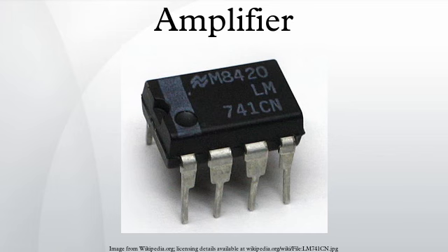AM detector circuits that use amplification, such as anode bend detectors, precision rectifiers and infinite impedance detectors, as well as peak detector circuits, rely on changes in amplification based on the signal's instantaneous amplitude to derive a direct current from an alternating current input. Operational amplifier comparator and detector circuits.